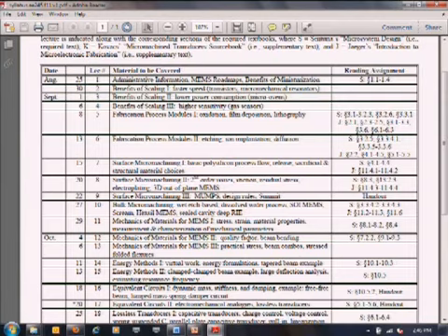So if you're a MEMS researcher, never cry about your process, right? CMOS is much more difficult, all right? But MEMS is only easy when you know how to control things like stress and that. So you will learn how to do that in this class. We'll go through a lot of this mechanics of materials here. Then we'll start talking about how to actuate these things, right? Because if you have a tiny structure, you don't want to actuate it by physically pressing on it, right? There's really no good way to do that. Usually you have to actuate it by applying voltages. And so we have to think about transducers, things that convert energy from one domain, like the electrical domain, to another, the mechanical domain.